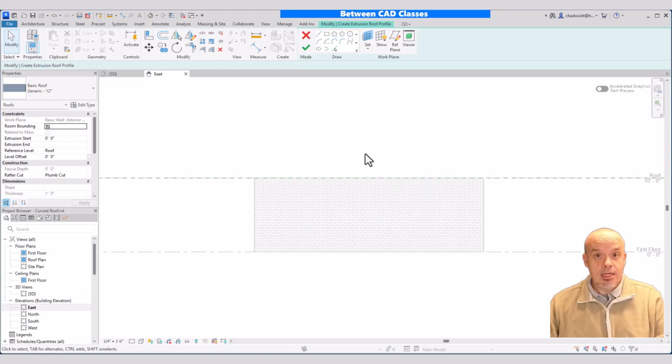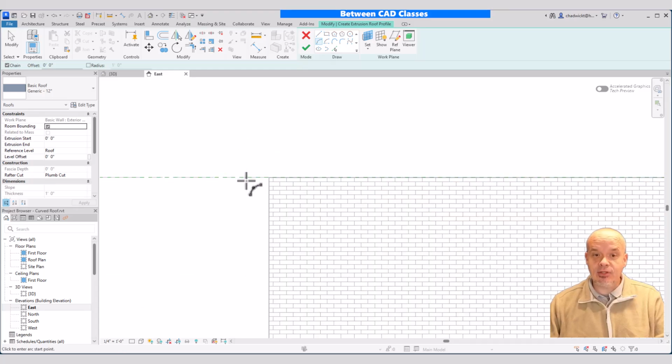this roof. Now on my roof, I want a 2-foot overhang in each direction, and you'll see that when I start the arc tool, it's difficult to do because the default dimensions go to the center of the wall there. Now, if I know the thickness of that wall, I can do the math and figure it out, but I don't actually know the thickness of that wall, so I'm instead going to draw a couple of construction lines.